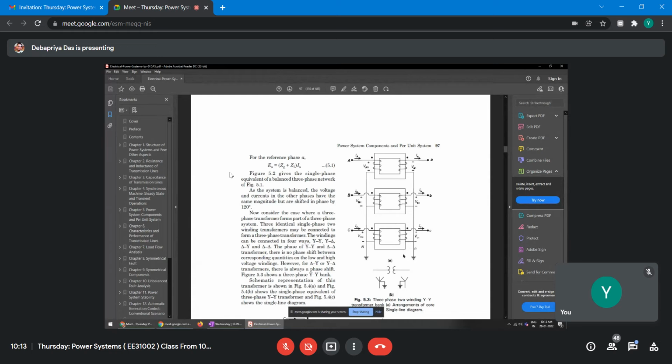But if three single phase transformers are connected as a three phase, and one phase has something wrong, say an insulation problem or a fault has occurred, then that particular unit can be removed from this three phase and taken away, so the cost of transportation and other things will be less. So in reality, all the power transformers, whatever three phase transformer you see, are basically three single phase transformers made together, right, to make three phase according to the high voltage side and low voltage side, accordingly it is designed. So for large transformers, basically three single phase units are connected as three phase.